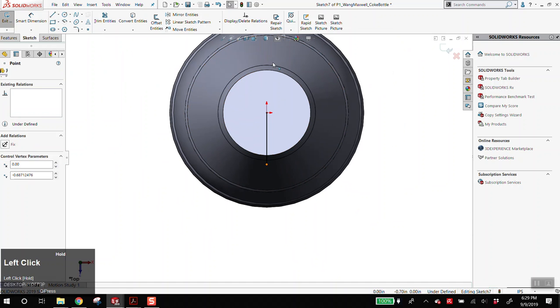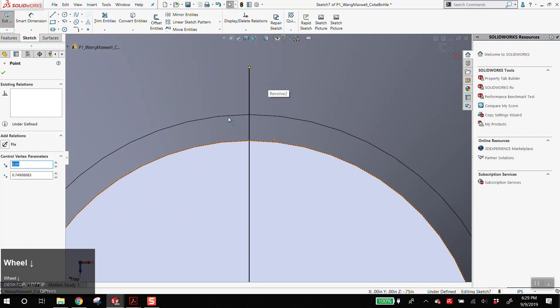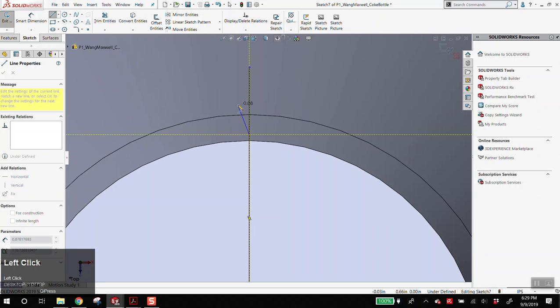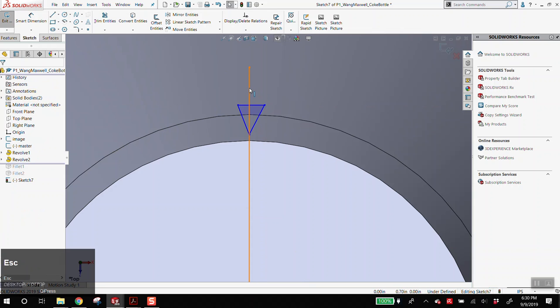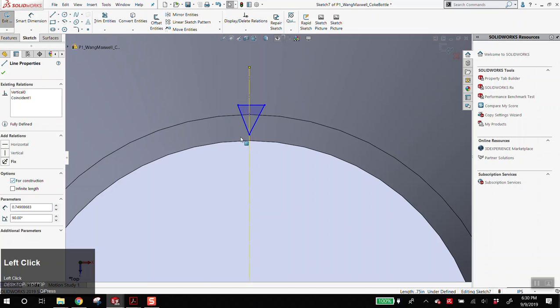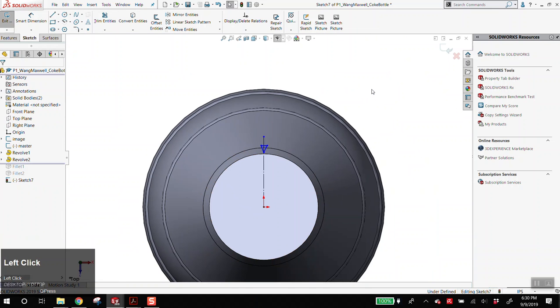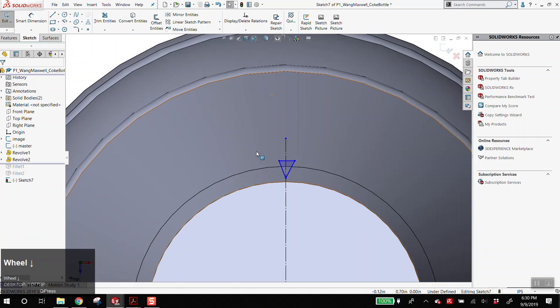It's kind of dark. I apologize. We'll go to the top so you can see it a bit better. And I'm going to just sketch a V on here. And we're basically just going to cut this. We're going to cut this, do this as an extrude cut to get that wedge in here.